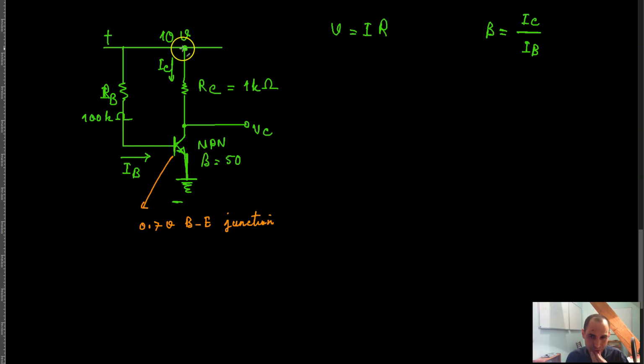When the power supply is greater than or equal to 10 volts, they just simply ignore the voltage drop across these PN junctions, which is usually assumed to be 0.7 volts. And of course, if you're working with a germanium transistor, the PN junction voltage drop would be something about 0.3 volts, which is next to nothing.